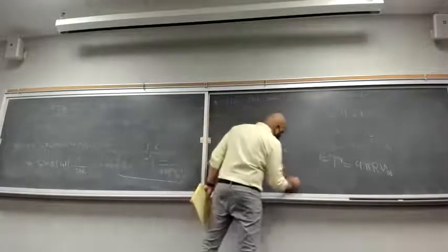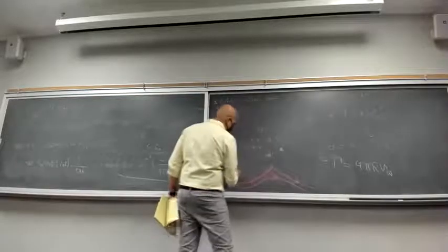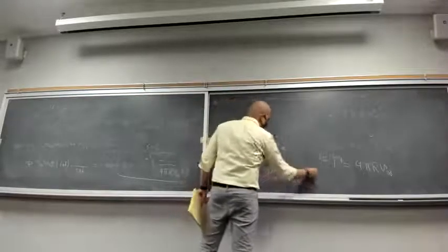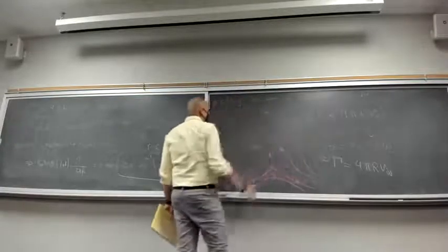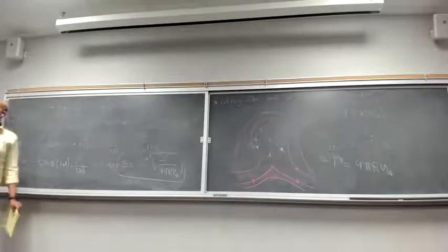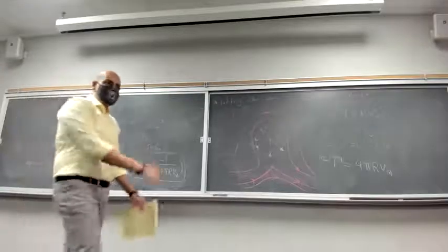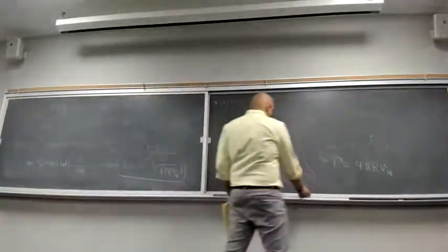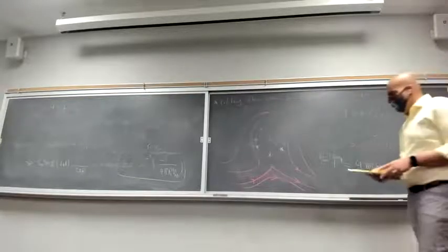The stagnation point for the third condition is not going to be on the surface of the cylinder. So this value of the strength of the vortex is very crucial here in determining where the stagnation points are.